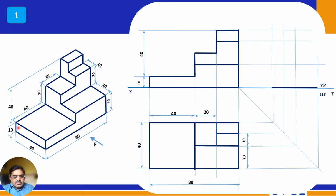It is the side view. So from here to here 10 mm plus 40 mm, so totally 50 mm will be a straight line, right? And then this 10 mm is a straight line, and then it will come down for 10 mm, right? And then this is 10 mm, draw 10 mm, and then 20 mm you have to come down, and then horizontally 20 mm, and then draw a vertical line, right? So this is the side view, and this edge is visible, this edge is visible. So obviously this edge is visible, and then this edge is visible, right?